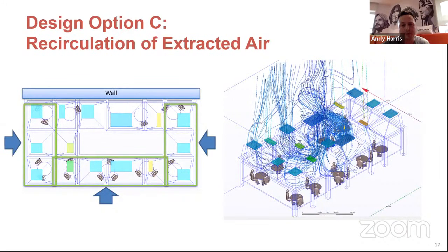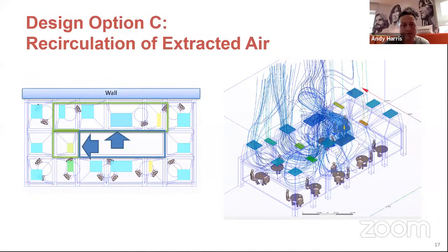So where we have the air coming in from the outside, we've got good feed of air to the tables around the outside edge, marked with the green boxes. If you click again. And then most of the air for these other outlets, these are the fans marked in the green box as well, is being fed through that center opening in the roof. However, a little bit of the air is actually feeding some of the other chimneys, which is absolutely fine for it to do. So that worked okay. If you click again, it should show the problematic chimney. That was the main one that was causing the recirculation. Click again.